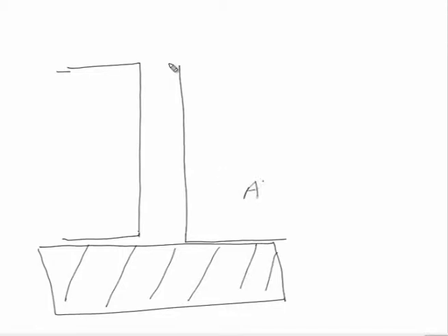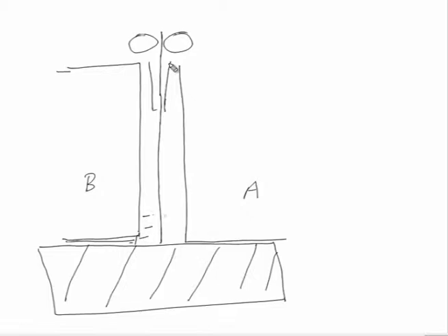So, this is plate A and this is plate B, and the electrode is fed through the rollers, and then it is fed with the help of a tube, that is the conduit pipe, to direct it so that it can strike the arc, and this region is initially filled with granular flux.